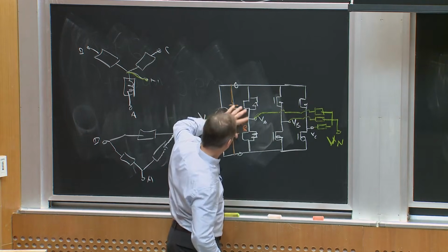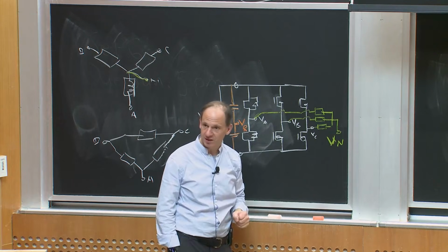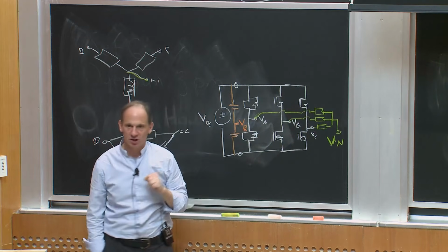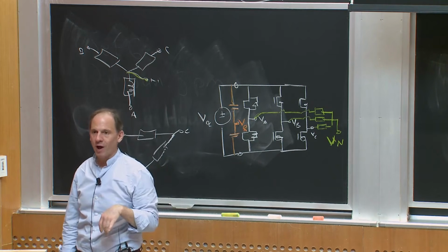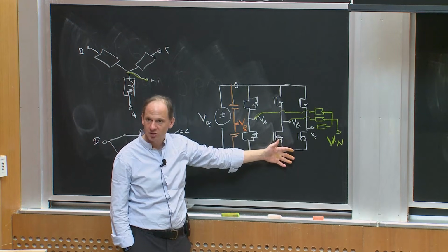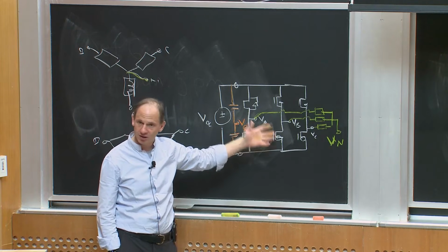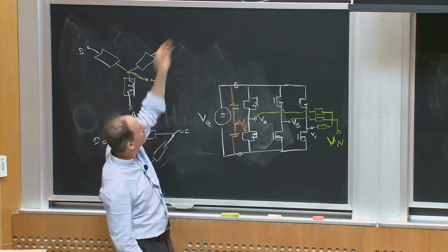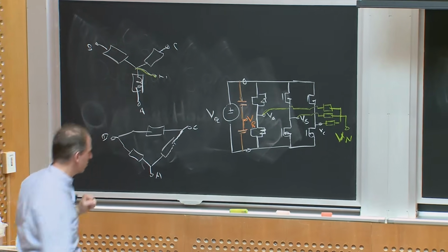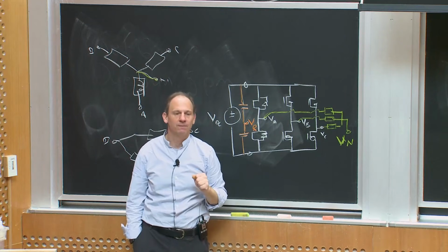Because this circuit, like this phase leg, whatever current goes out, it returns through one of the other phase legs, I get an advantage in terms of the utilization of the devices. So I will either require less semiconductor area to get a certain conduction loss in this structure, or I will have lower conduction loss for the same semiconductor area, compared to the top solution. So this solution in most 3-phase applications is vastly preferred.